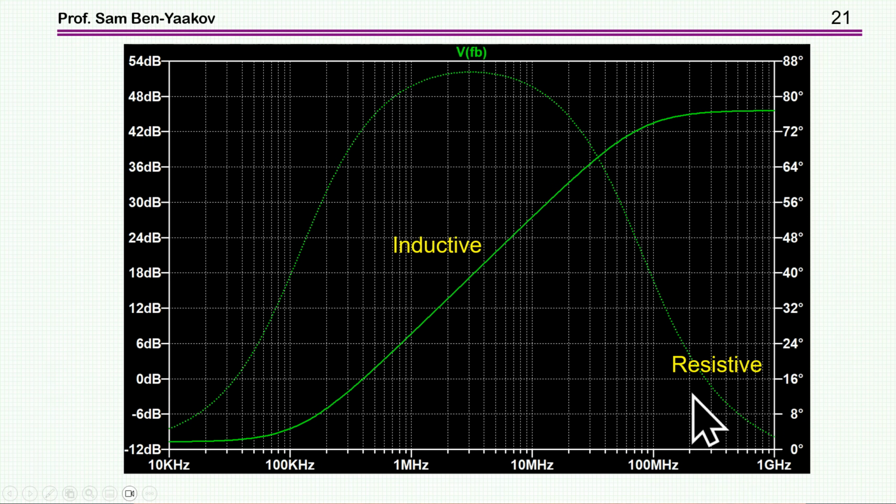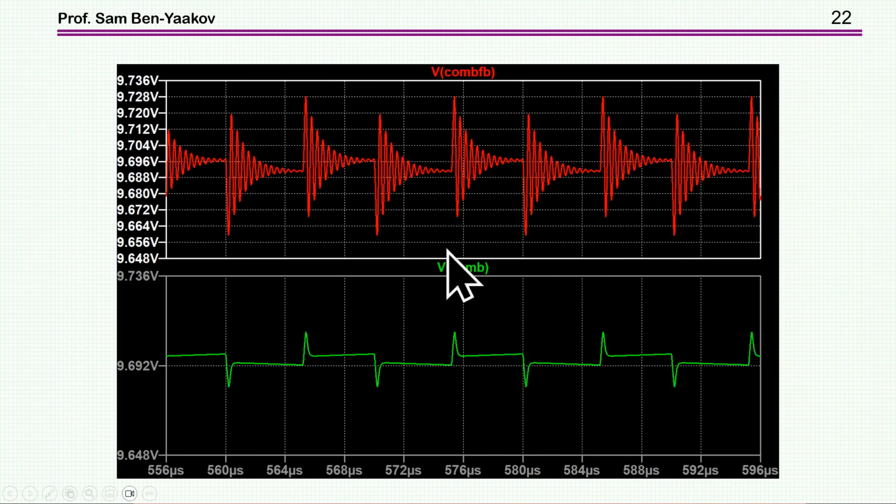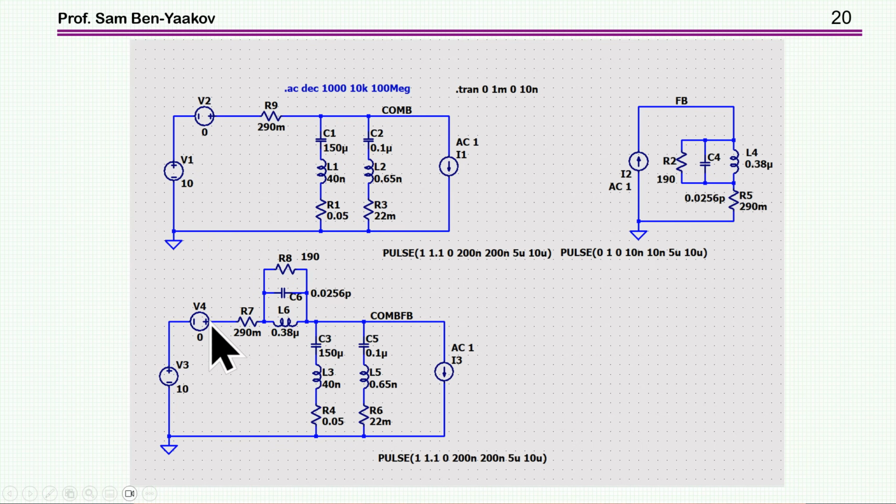It's too far away. This is the region we are interested in, so rather than putting in a resistor, we have put in an inductor. And this is what happened, because now, if I compare these two, this is without the bead, just the DC resistance of the bead, and this is with the bead. Looking here and here, this is without, and this is with the ferrite bead.